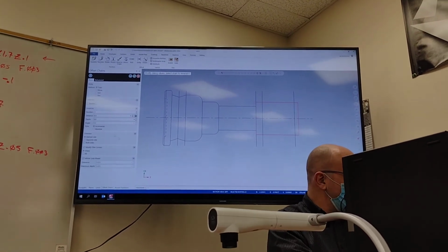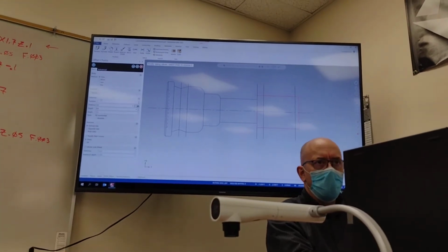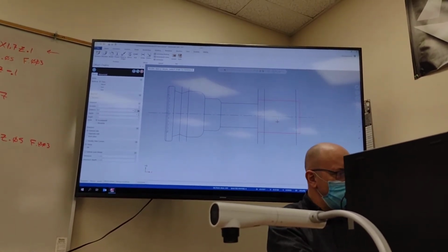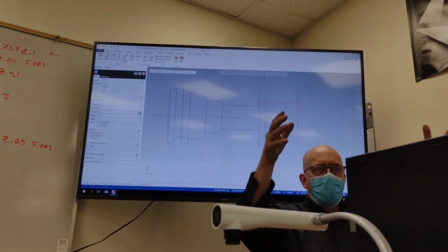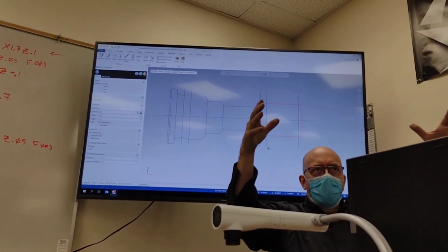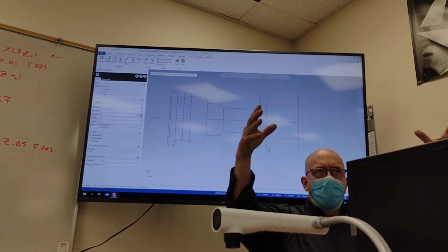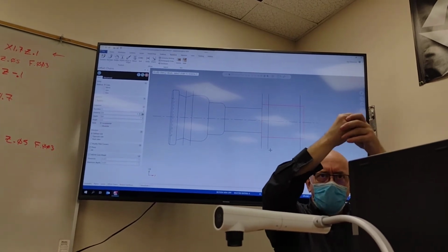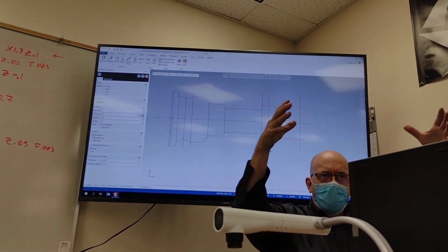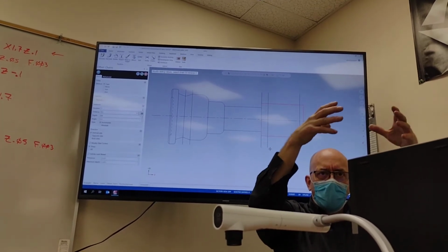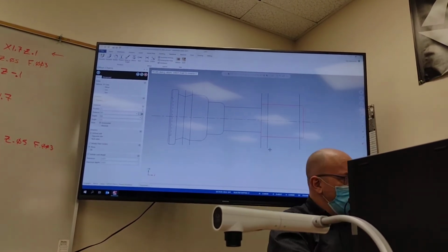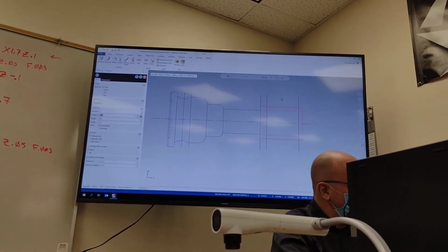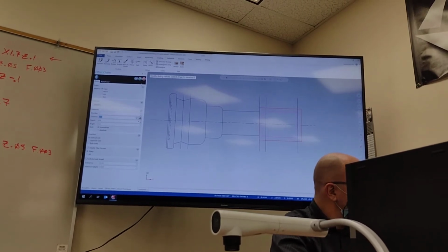Can you see my screen from back there? See this number right there? 500. That means it's too far. So it's like if you had a 2-inch diameter and you wanted to offset the diameter more than an inch, it would go past the center and it wouldn't work. So you can only collapse it or offset it less than half. So this number is too big right here. If I make it 60, see, look at my little line? Yeah. Let me click OK.